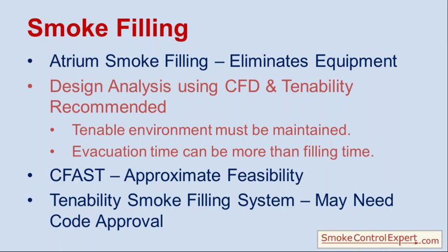Design analysis, I strongly recommend using CFD and tenability analysis when you're designing these things. You want to maintain a tenable environment, and that's the approach that gives you a high level of confidence that you do maintain a tenable environment for the design fire. Evacuation time, in fact, can be more than the filling time because you're maintaining a tenable environment.